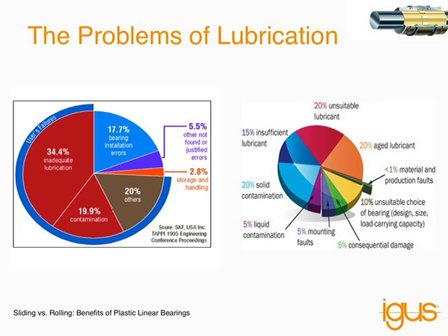That could be from parts not being maintained correctly, or grease not being administered at the right time or improperly. There could have been an environmental problem where using the grease in dirt, say, caused an ingress of contaminants into the ball bearing, causing a failure. It could be related to any number of issues, but the number one cause of bearing failure in manufacturing is bearing lubrication related.